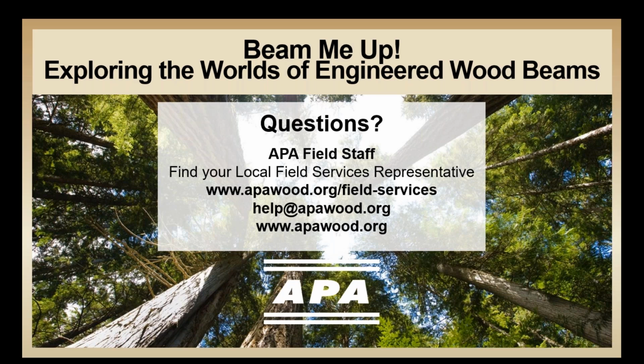But if you really think about how structural composite lumber is made, even in LVL, they're quite often manufactured in billets that are 2 feet wide or even 4 feet wide. And essentially, when they come down to the shallower members, what they're doing is ripping those billets down to those depths. So structurally, you can. You just need to make sure you check your design values. So typically not a problem with this SCL, but not something you could do with glulam beams.